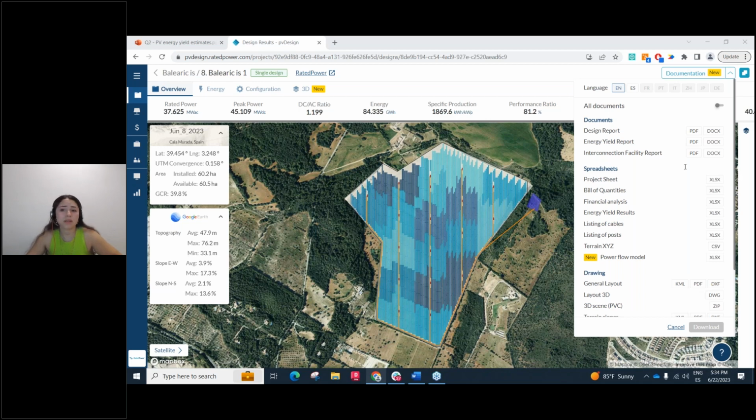This value is based on the PVsyst value, which applies for some meteo sources. But for example, if we take Meteonorm as a source, it gives you the exact uncertainty. So you need to see the source, and from that source you can get the uncertainty. So that value can be changed. It should not always be 3%. You can change it.